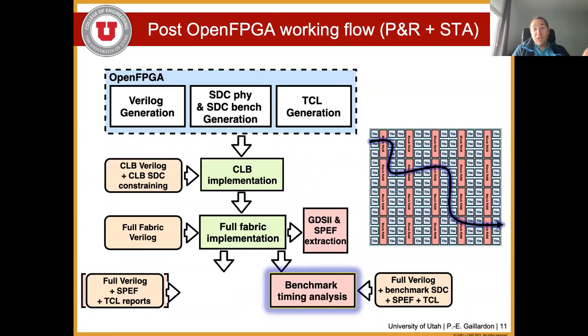Because FPGAs have loops all over the place. You cannot evaluate the performance of your fabric in a standard way using STA or using ModelSim. You need to provide constraints to cut the loops, extract the various timings you need, and reconstruct that. This is fundamental, otherwise none of your existing methodologies will work. That is part, again, of the framework to support all of that.